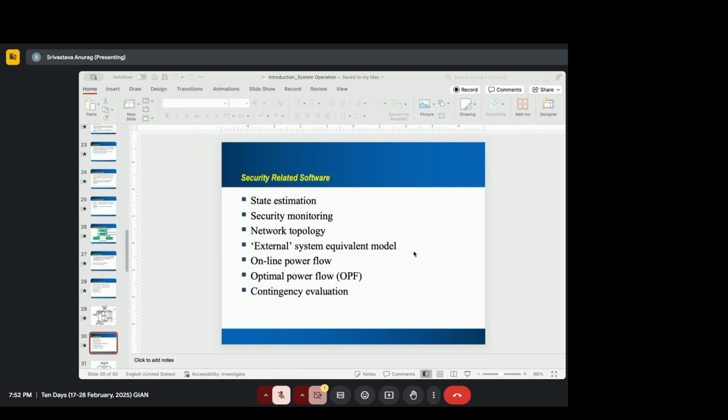So with the PMU, we can do a lot more, especially in terms of dynamic analysis, and in terms of integrating it together to do a single thing. There are roadblocks, which are mainly caused by the cost, because SCADA is slower than PMU. In terms of accuracy,